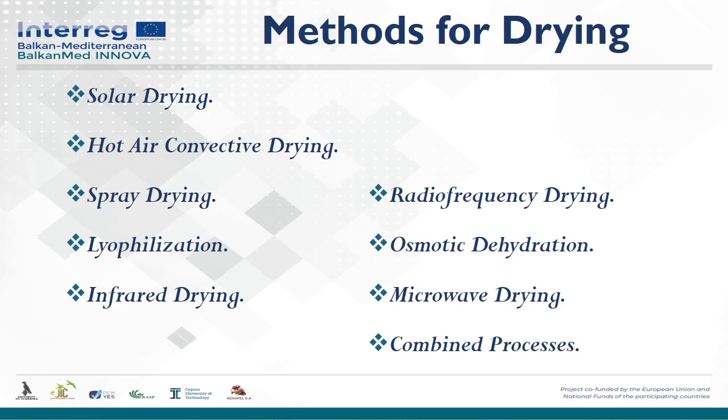Lyophilization is usually preferred to convert heat-sensitive materials into powder form. However, long processing times, low production throughput, and possible chill injury associated with freezing are considerable disadvantages of this process.